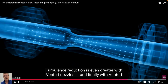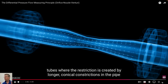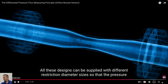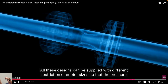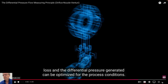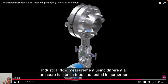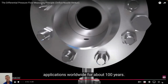But I guess the key thing here is that it's easiest to measure a pressure in a system rather than have a little impeller or an anemometer, which you measure wind speed with, these little cups, 3 cups that float around and go at a different speed based on airspeed. You measure pressure, no moving parts. Instead of measuring pressure with a gauge upstream and downstream, you have a differential pressure measurement, which measures just the difference in those pressures, which is what you need.